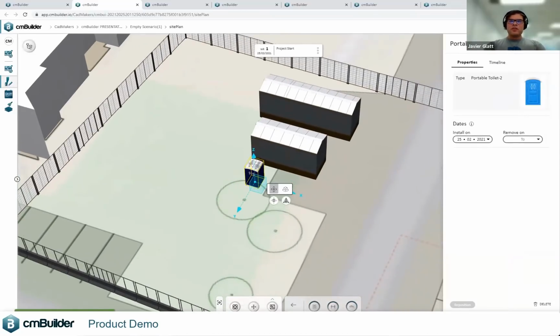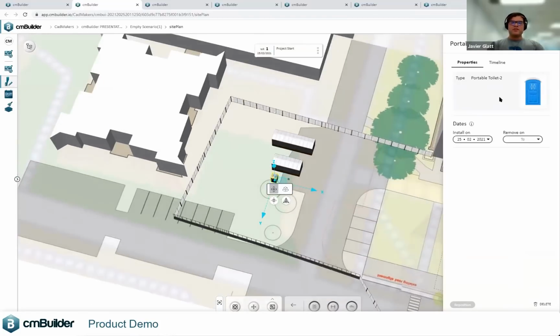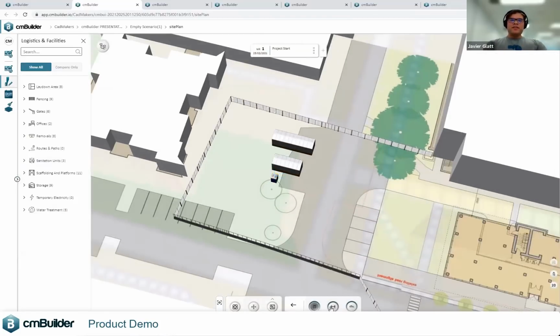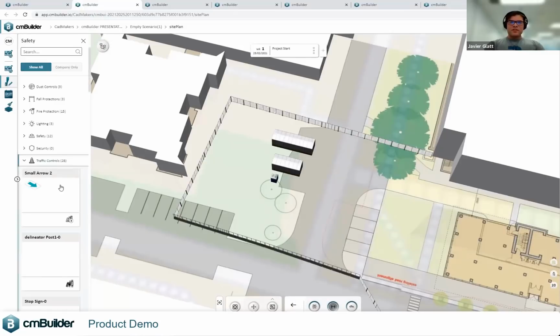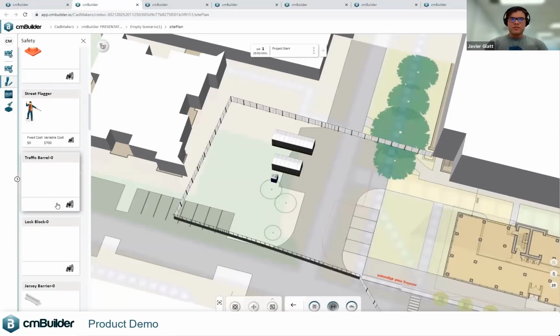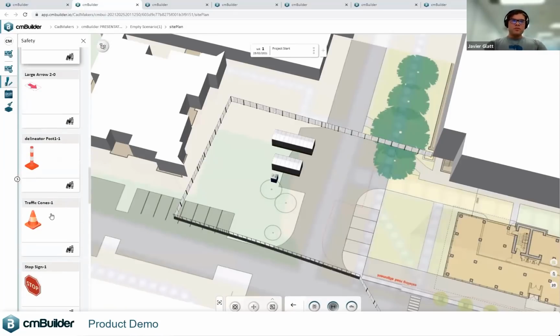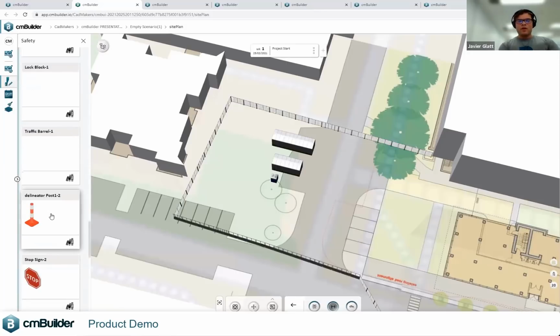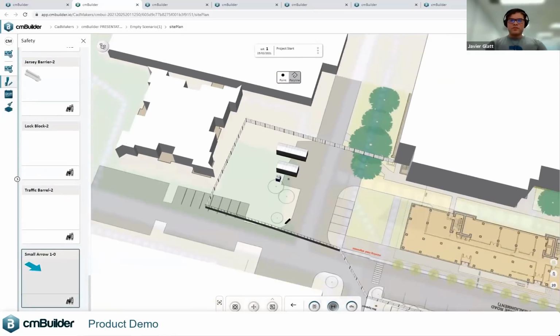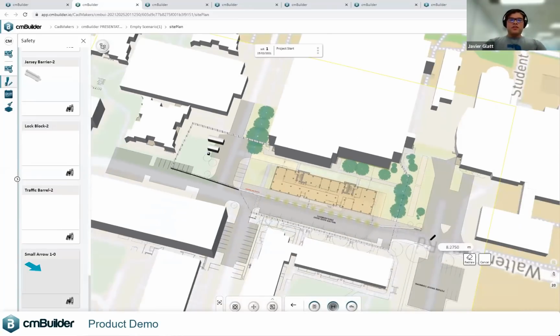Let's go to traffic control. Huge on just about every site, especially those downtown sites where you have really tight sites, postage stamp sites. So let's start thinking about logistics around traffic. So cones, are you going to have to shut down one lane of the road during construction time? Do you need flaggers? How many flaggers are there?